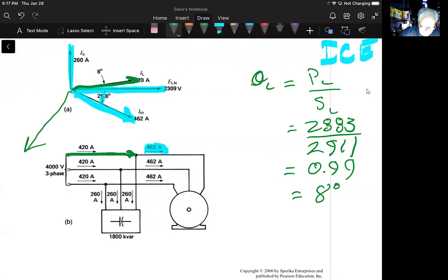He says, I want to emphasize the importance of assuming a Y connection, irrespective of the actual connection. By assuming Y, all the circuit elements are simpler and easier to understand. As a final remark, the reader has no doubt noticed that the solution of a three-phase problem involves active, reactive, and apparent power.